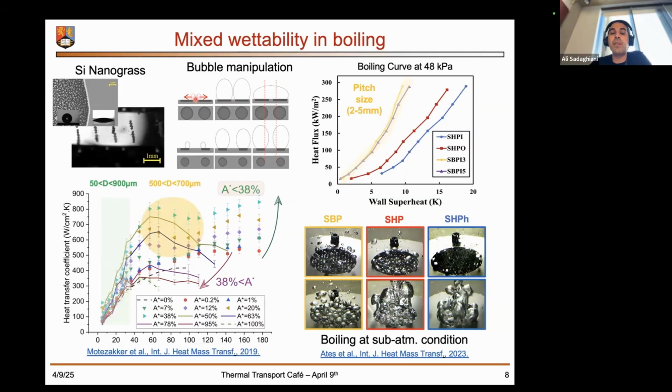What we observe in our experiments is that the boiling incepts at the contact line between superhydrophobic and hydrophilic regions. After nucleation, the growth of the bubble is toward the center of the superhydrophobic spots. If the edge-to-edge distance between the hydrophobic spots is small, we observe bubble coalescence, and bubbles basically cover the superheated surface. And as the space increases, we start to observe bubbles forming perpendicular to the superheated surface.